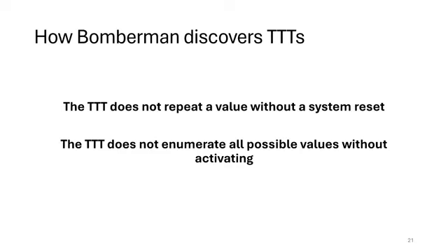So if we have these specialized attacks that fly under the radar of general purpose approaches, then the solution is clearly to develop a specialized hardware check. So they call this Bomberman, which looks for state-saving components that don't repeat a value without the whole system resetting, and doesn't enumerate all possible values without activating.